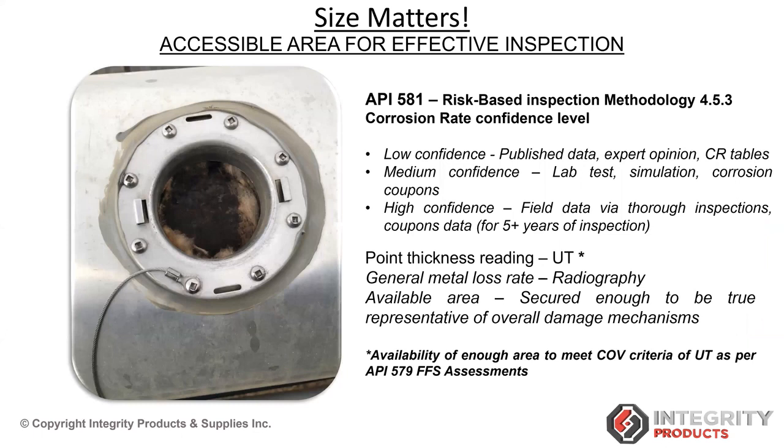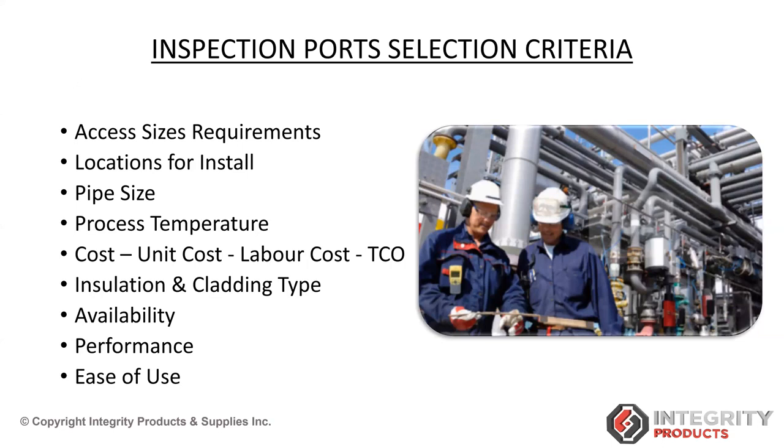Like in the picture that we had here, Ahmad, if you have an inspection port allowing water ingress due to poor performance and lack of sealing, with actual water ingress points built into this old style of port, which we display here, you're really defeating the purpose. You're going to find corrosion right where you're looking for it because you're using a poorly performing inspection port. Yeah, absolutely. And also, imagine that it's a medium pressure steam line. Let's say the temperature of the steam is 200 degrees Celsius. How much heat loss would we be expecting in the cold weather of Canada?